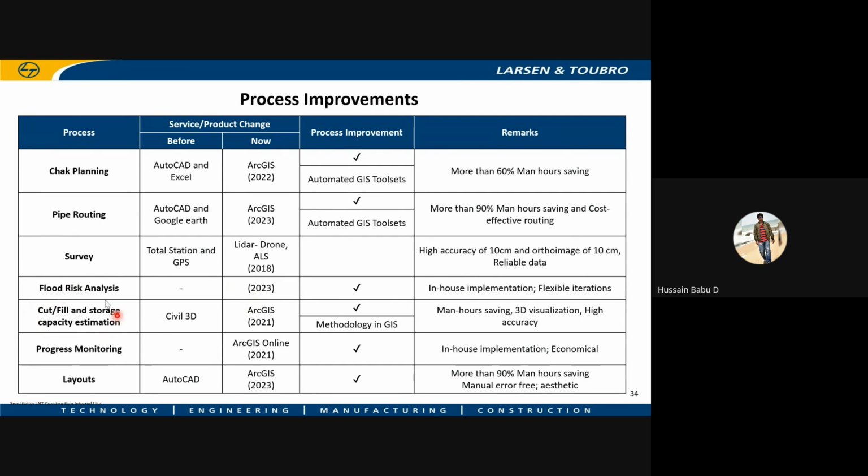For cut and fill and storage estimations, earlier it was done with Civil 3D or manually in Excel. Now we are doing it with ArcGIS, and we have developed a methodology in GIS by which we do these processes for all our dam constructions and intake and pump house excavations.